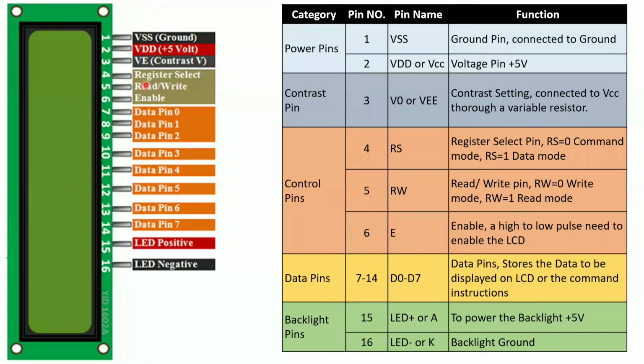Okay, the next one is the read or write pin. You may wonder, sir, we are going to write the data to the LCD, that's why we are using the write pin, then why are we using read mode? Is it possible to read the display? Yes, I told you the LCD display has an inbuilt controller, so that controller has some commands. Suppose you want to know which command you have given previously, you can read that information with the help of this read mode.